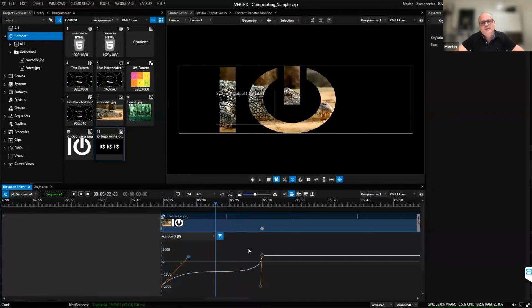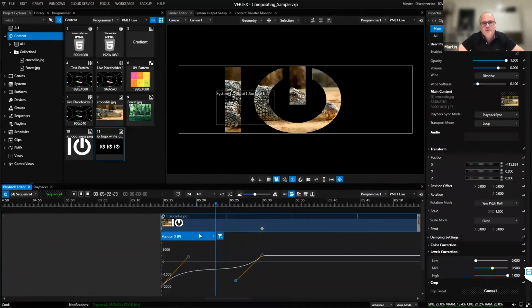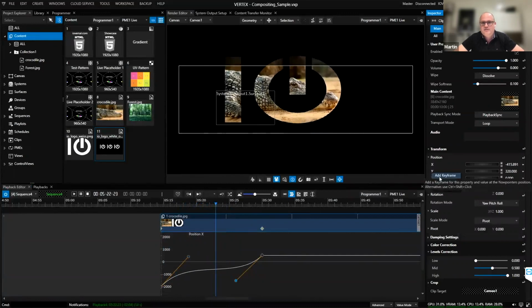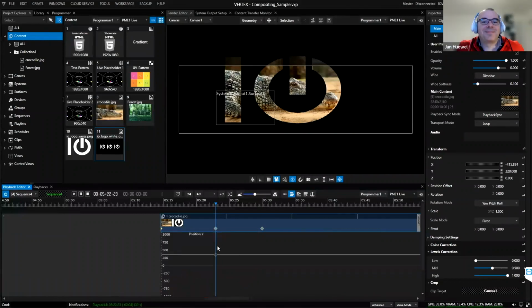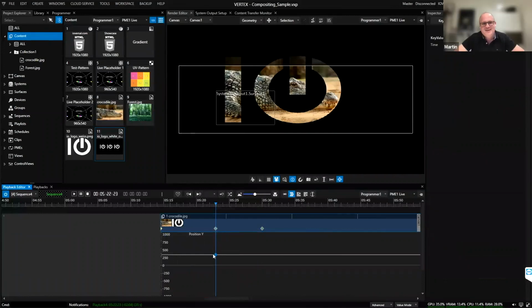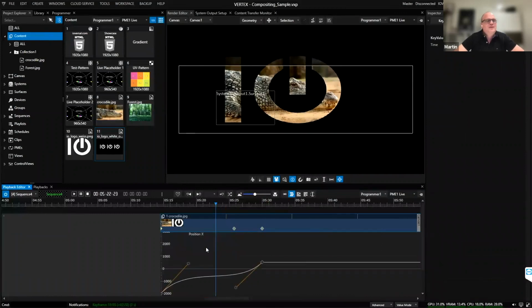So this really is where you can program animations for whichever property you like. We've done it for one now, but you can see here we have a filtering. So I can see I've only used X position. If I go ahead and set a keyframe for the Y position, I can now either switch the filtering here into seeing every possible keyframe, or click on the filter again. I'm missing the click. There we go. Yeah, only see the Y position. Yeah, only see one position, which I can now work with in different keyframe tracks, so to speak, to create